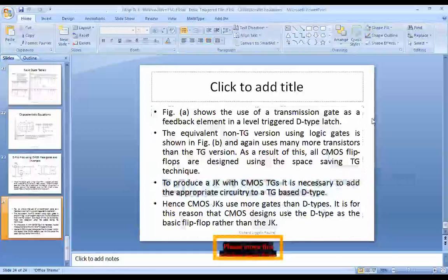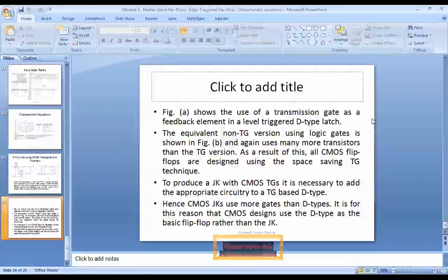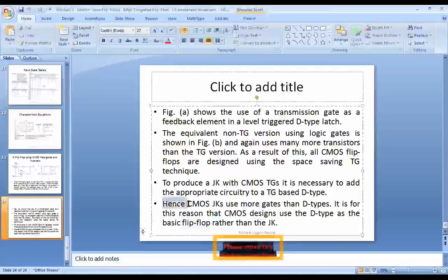your normal circuitry. Now that can be done with the help of equations. So once you have the equation, as you all know how to develop a CMOS circuit, where PMOS is at the upper side and NMOS is at the lower side. PMOS is connected to VDD and NMOS is connected to ground. So ultimately, based on the serial and parallel combination that we discussed, any CMOS circuit can be implemented.